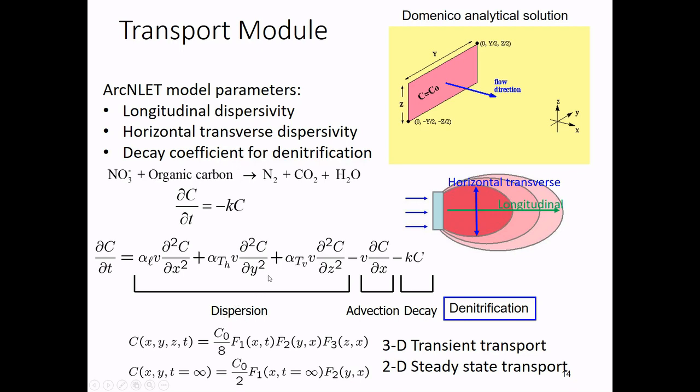And the amount of dispersion is actually governed by the parameter we call dispersivity. And we have essentially three dispersivities. One is the longitudinal dispersivity. That means it's going to disperse out along the flow direction. And then we have the so-called transverse, and we have a horizontal transverse. This is a bird's-eye view of the plume. It's not a vertical cross section.